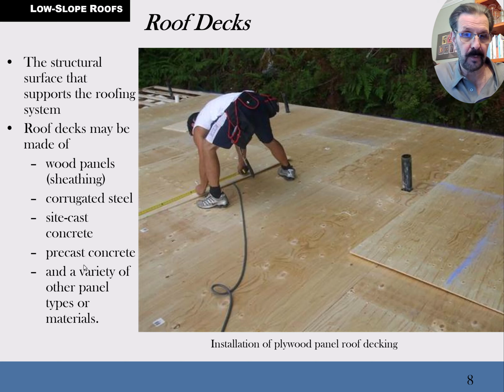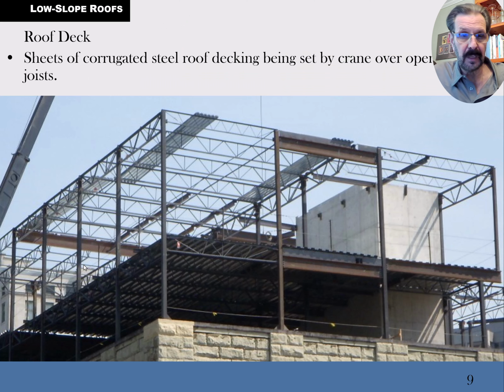And if you've got plywood as your roof deck, well, it's flammable. So if it's a commercial roof, you're going to have to protect it with fireproof material. So they put down a fireproof material like drywall. And you say, drywall on the outside of a building? Well, we do it all the time.